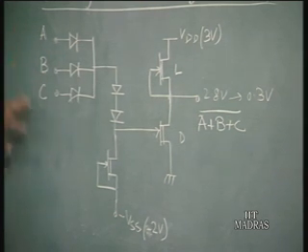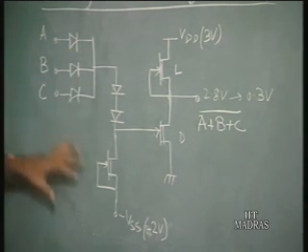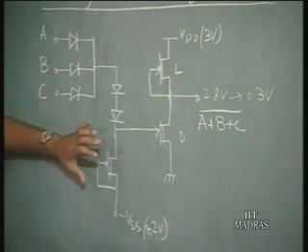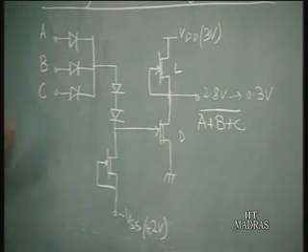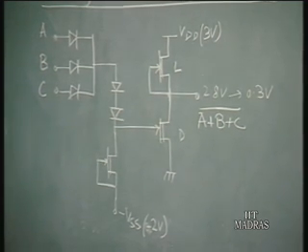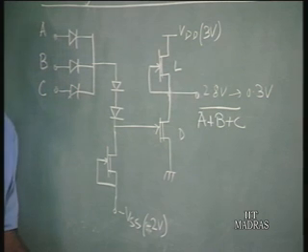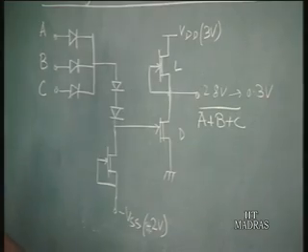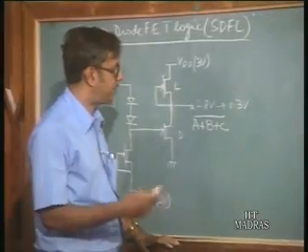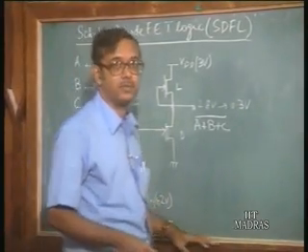Okay. So, this logic is performed using mostly Schottky diodes, and as we said, the Schottky diodes have less area. So, this is suitable for large scale integration. So, in fact, you can have a lot of variations using the Schottky diode FET logic family. For example, you can have OR and invert type of operations.